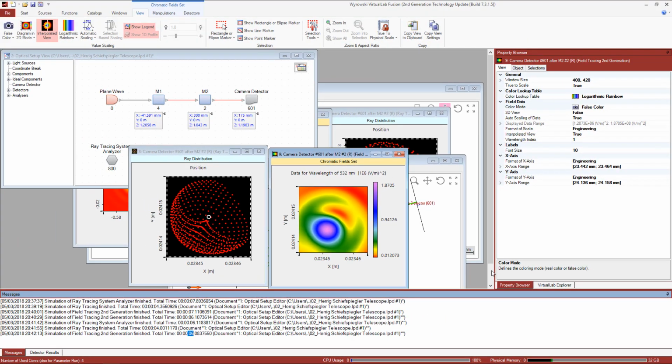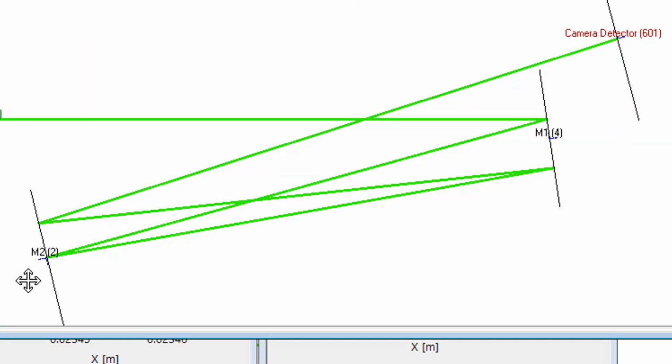This is the first example I want to show. In fact, here I still want to stress the channel definition. We must first identify the z-axis of the local coordinate system of each component, define the direction, and then define the channels. Although this setup looks quite similar to the Etalon, because of the local coordinate system, the mirror is opposite. The channel definition is not the same as the Etalon.